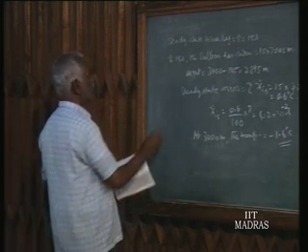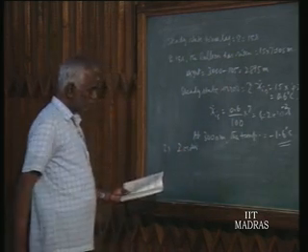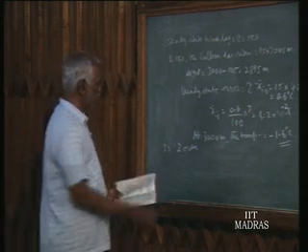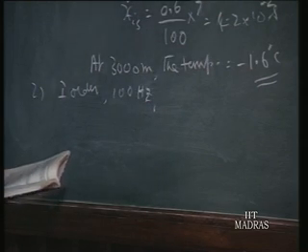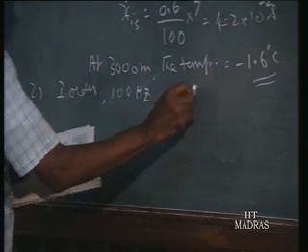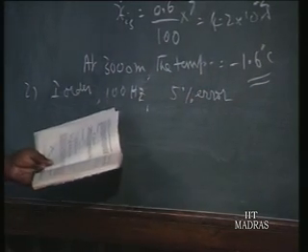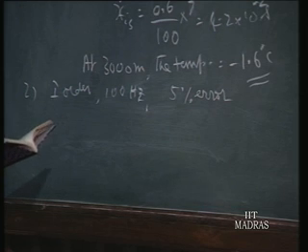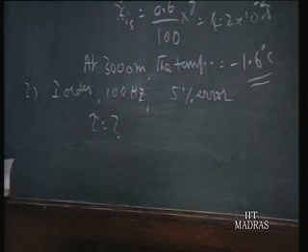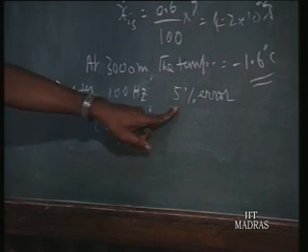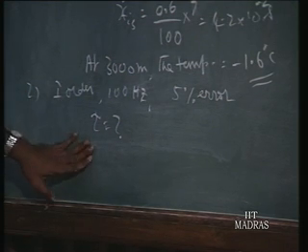Problem 2. A first order instrument measures signals with a frequency up to 100 hertz, with an amplitude inaccuracy of 5% error. Then calculate the maximum allowable time constant. What should be the time constant of the instrument if it has to measure with 5% error and handle signals up to 100 hertz, and it is a first order instrument?